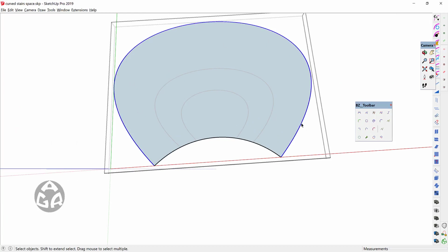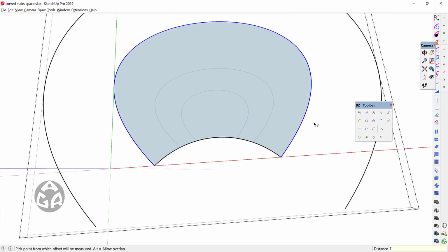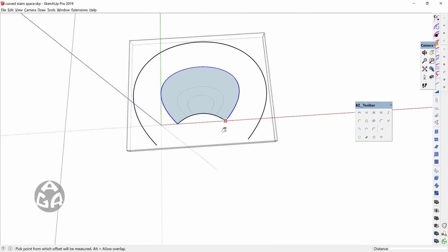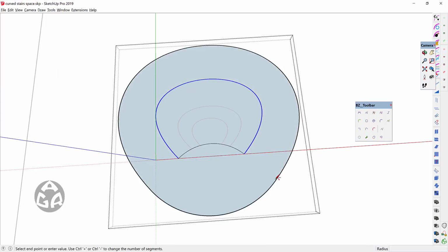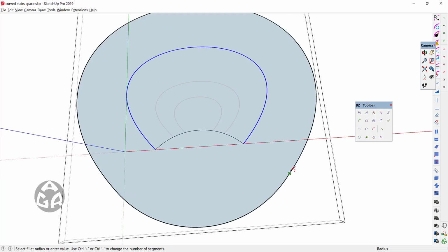And also we will offset this curve by about 7 meters, and we will create an arc as a tangent at vertex, and we will double click over here, so this will create, as you could see, a purple color for it, and it did create a tangent curve for this curve that we had.